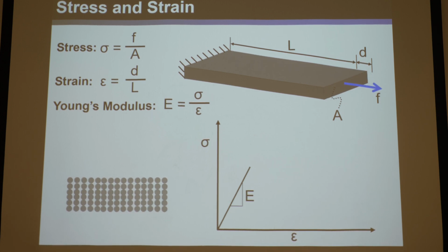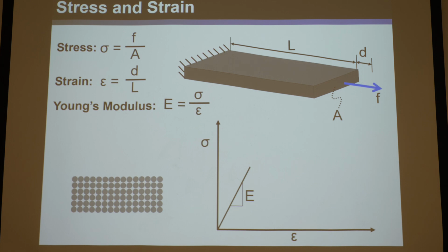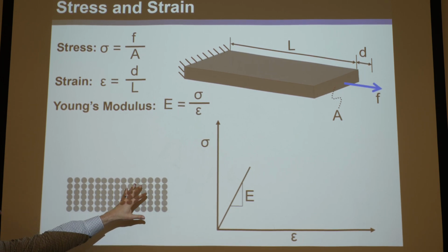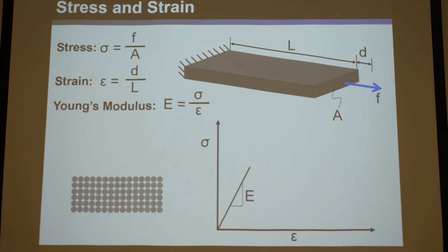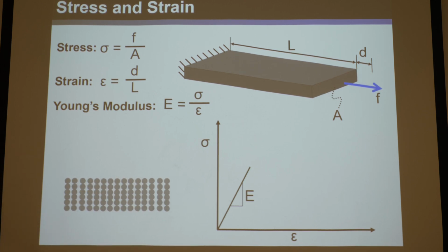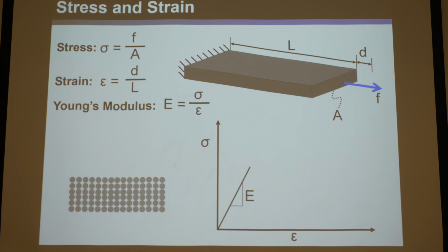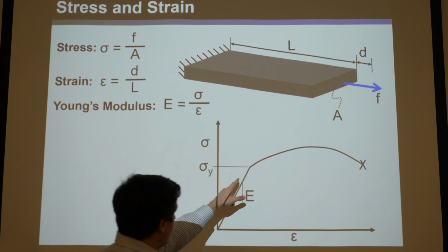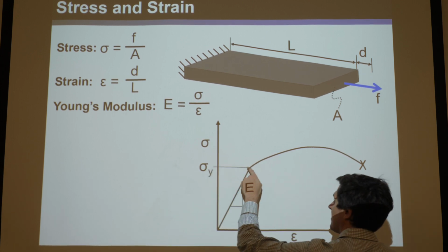This is why they don't generate friction, internal friction anyway, and hysteresis and things that are bad for repeatability, right? Now, of course, they do, as we'll talk about, but for small deformations, they effectively don't. They're very repeatable as long as you don't stress them too far. But if you stress them to the point of yielding, this is the yield stress,